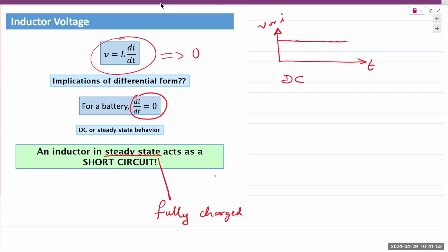I will repeat. When you apply an input current to the inductor, you have a magnetic field. That magnetic field will give rise to an opposing voltage that has polarity that is opposite and opposes any change in the input current. It does not oppose the current itself, but it opposes any change in the value of the input current.